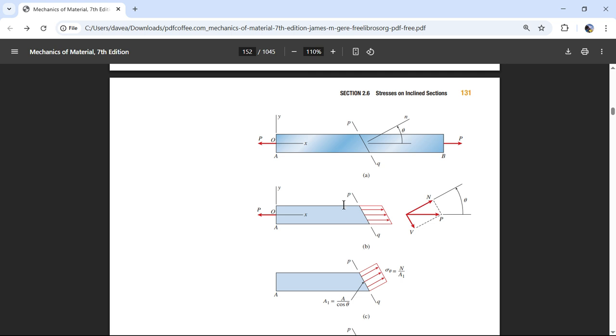And that's the most important part about material mechanics: we're interested at any little point on a material. We basically have properties of that material. It can take a tension, and I wouldn't call it tension. You would say it can take a normal stress. It can take a tensile stress, which is tension. Tension would be a force, but it can take a tensile stress of 58,000 psi for steel.